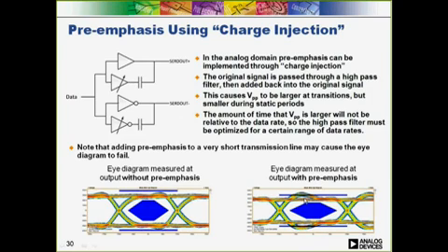Now, violating the limit is really not that big of a deal from the aspect of being compliant, since there's no JESD204 certification required for users implementing it. The bigger concern may be from any resulting increase in EMI.